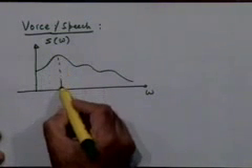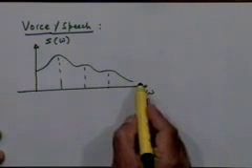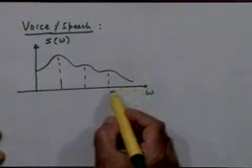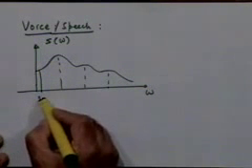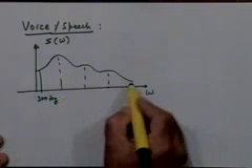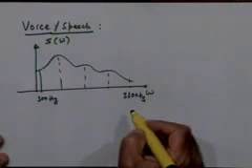As you will see, there will be a few major peaks in the spectrum, but on the whole, the spectrum will start decaying after a few hundred hertz. And for telephonic communication, it is found that if you concentrate on the energy between 300 hertz to about 3300 hertz, right, you capture most of the intelligence as well as essence of speech, without losing much on either the intelligence or, let's say, the quality of speech, right.